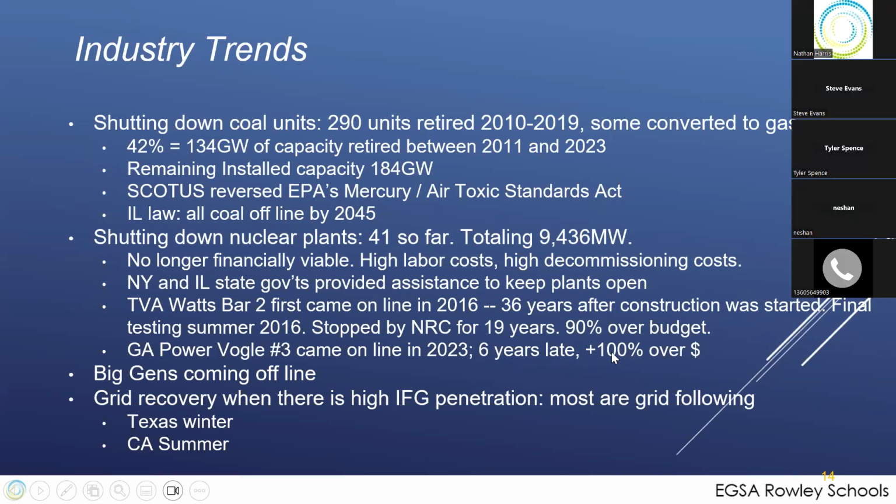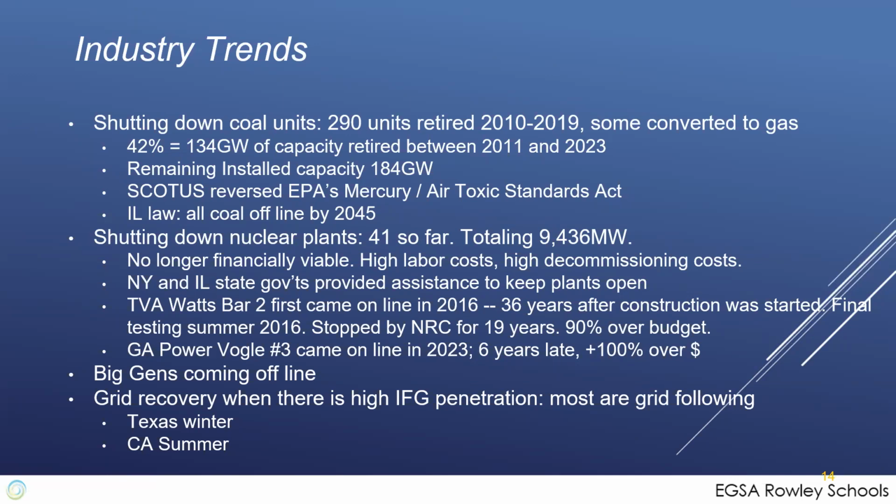So nuclear is there. It's been a solid backbone, with high capacity utilization, but it's really not enough to do what we need to do. And we're having trouble with grid recovery. Those of you that deal with small markets understand this real well: if you have a lot of inverter-fed generation, especially single-mode inverters, bringing it back on after an outage is a problem.